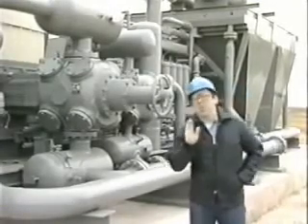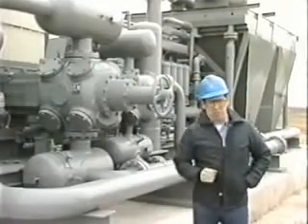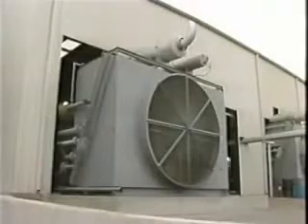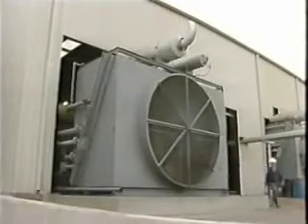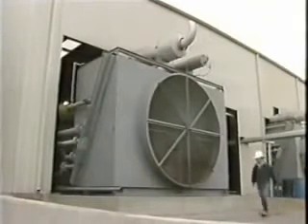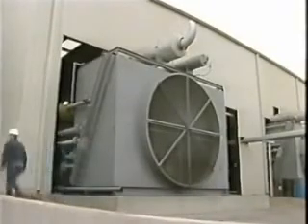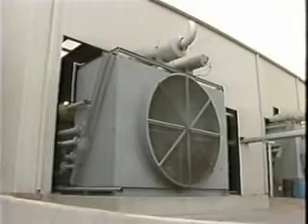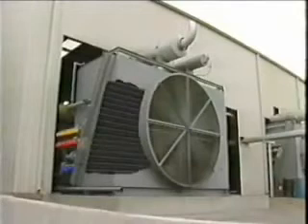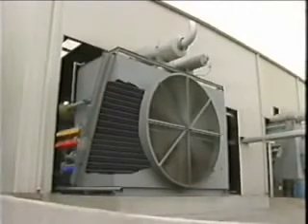All right, let's spend some time now talking about cooling systems. The purpose of the cooling system is to prevent overheating. Overheating can cause compressor damage, and that means costly repairs. In most cases, there is a single cooler used for several cooling purposes. The cooler may have multiple passages for lube oil, jacket water, and the compressed gas stream. That means the compressor and internal combustion engine can be kept from overheating by the same cooler.